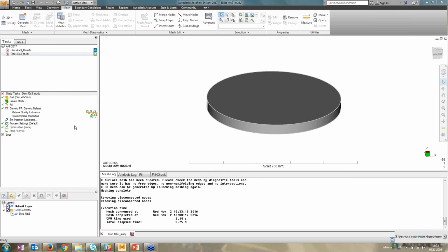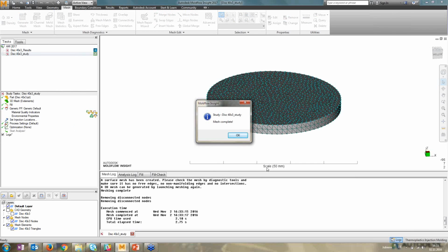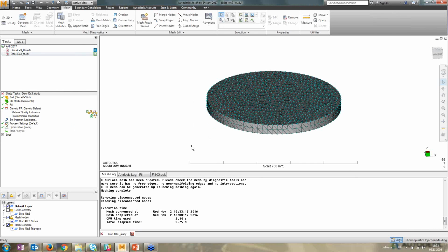So the part should be placed on the cavity space that I have on the mold. If not, I will get some errors. Therefore I stopped the meshing at the surface, because I need one node placed on the 0, 0 coordinate for modeling my beams for the gate.